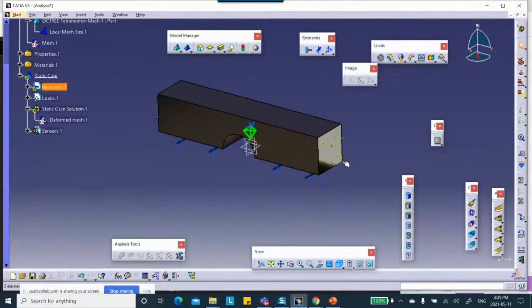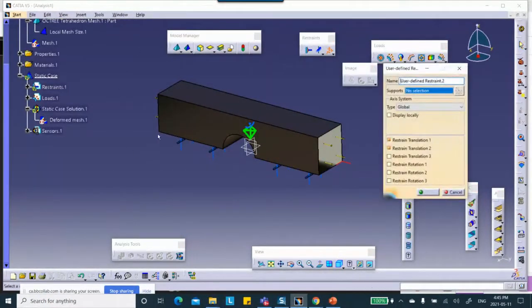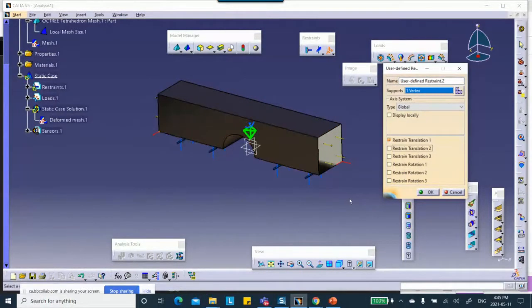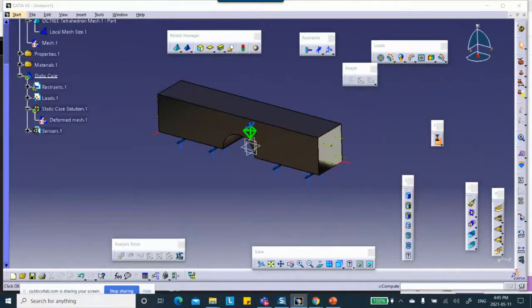As if somebody grabbed the corner of the fridge on that point, somebody else can still push it in the XY plane. It's going to spin about that point. So we need one more point so that it does not move in the direction X. This can no longer spin, okay? Or you could have taken that point, or you could have taken that point. It really doesn't matter. Sometimes I make mistakes too.